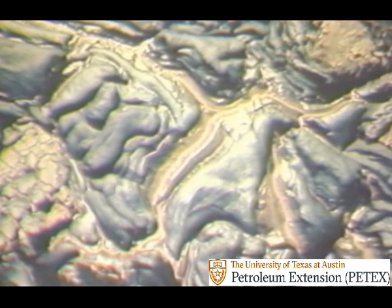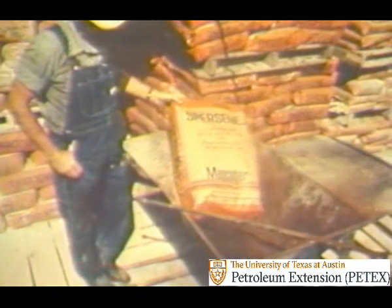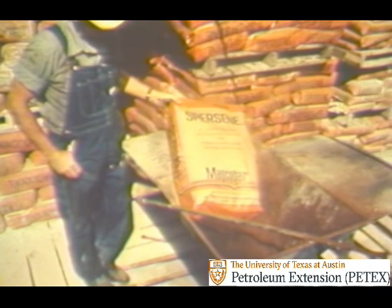The most serious problem with calcium mud is that it solidifies at high temperatures. This problem is most severe with lime mud, but both gyp and calcium chloride muds also solidify. To overcome the solidification problem, chrome lignosulfonate muds are used. The derrick man here is adding a lignosulfonate with the brand name of Spersene. Lignosulfonate muds are inhibited muds that offer many advantages that calcium muds do not have.